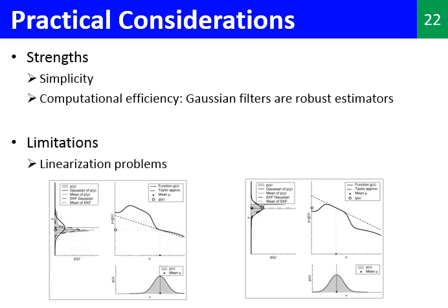Okay, so we can learn two things from this. Number one, we have to accurately model the state transition and measurements as much as possible to benefit from the strengths of the EKF. Number two, if the problem is highly nonlinear, we should seek other nonlinear estimators such as particle filters instead of extended Kalman filters.